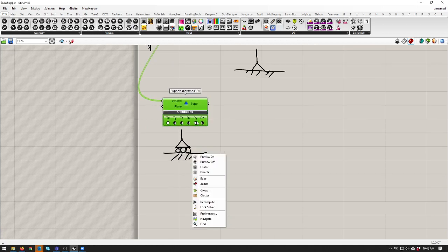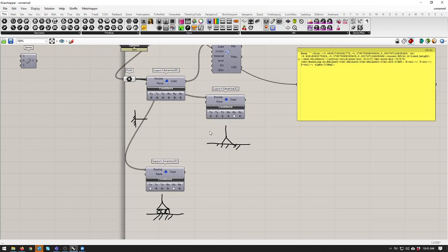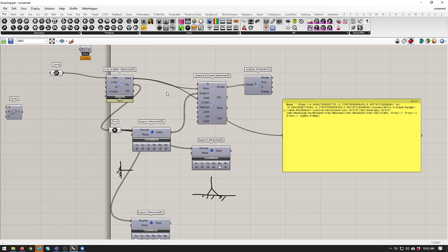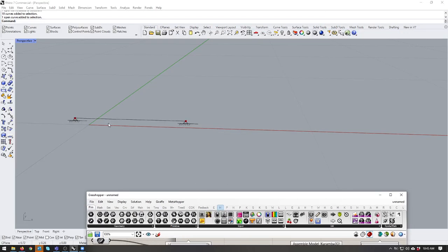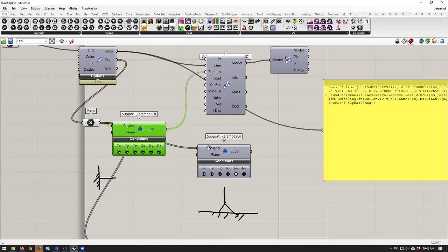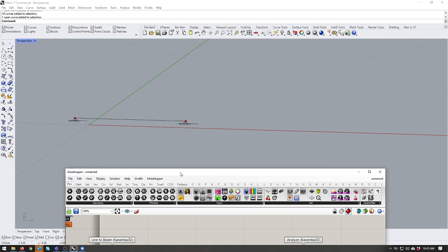Does that make sense? These simple diagrams that we've drawn for rigid pins and pin roller joints, supports, sorry, we have a lot more control over that by effectively defining the axis of movements with this support system. So if I want to actually draw what I've drawn here, then we want to use this support to help model our system. Have I lost anyone?